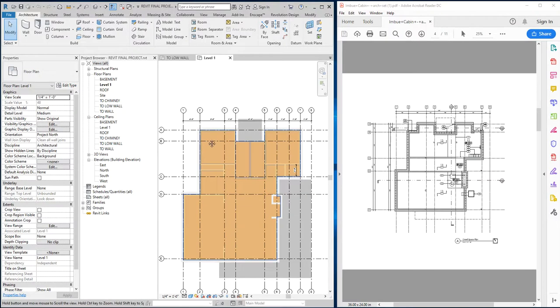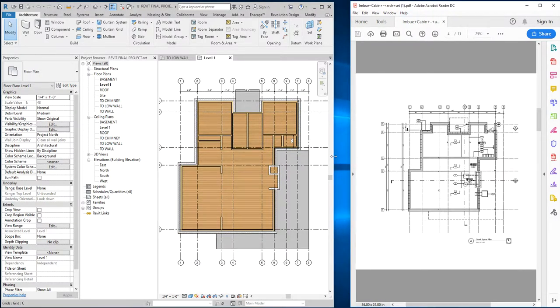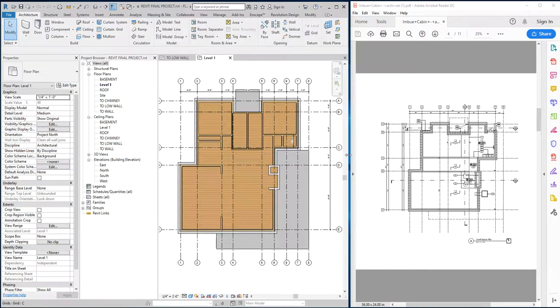And the reasoning, I think, behind that is that in Revit, the best way that I have found to add basement walls is to add them from the main level, funny enough. Even though they're basement walls. So you think, well, I want to add basement walls in the basement, right? But the reason I like to add the basement walls, and I say basement walls meaning in the form of foundation walls, so we're going to be adding foundation walls around the perimeter.